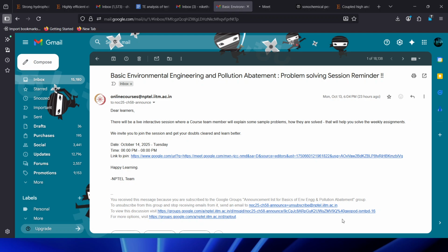Depending on the type, biomedical waste is divided into 8 categories. We are not going into that now. So we look at how this waste can be managed. First step is collection. The waste must be collected separately and stored separately so that it doesn't contaminate other wastes.